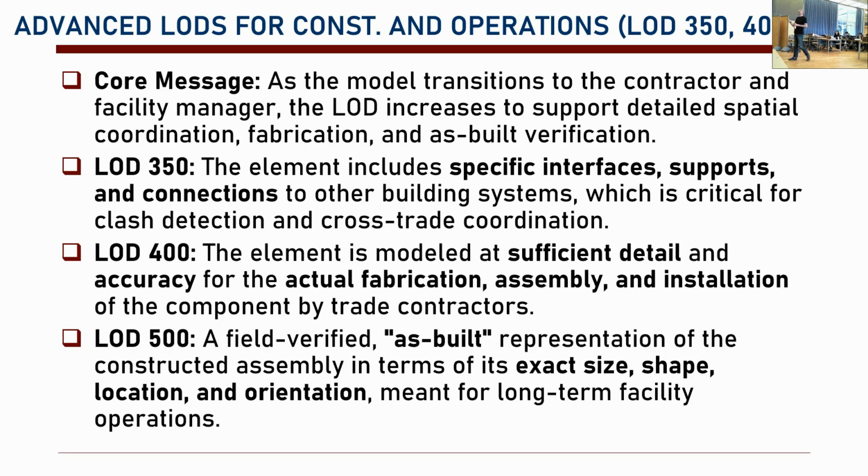LOD 350: specific interfaces, supports, connections to other building elements. Some people say that LOD 350 is a mixture of LOD 300 and LOD 400. Okay? LOD 400 is the element modeled in sufficient detail and accuracy for actual fabrication, assembly, and installation.